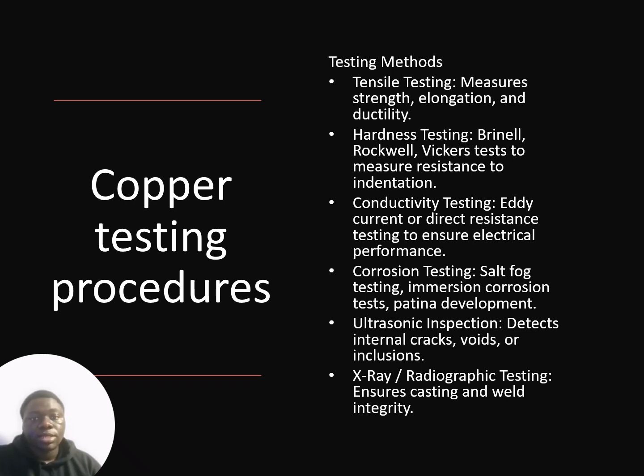For corrosion testing, they use salt fog testing, immersion corrosion tests, and patina development tests. For ultrasonic inspection, they detect internal cracks, voids, or inclusions. For X-ray tests or radiographic tests, they ensure casting and weld integrity.